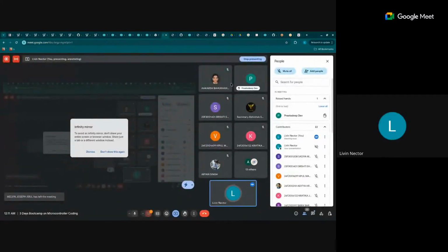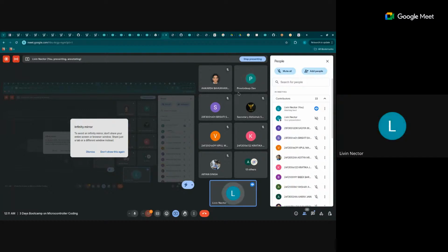A quick question, I'm sorry if it was discussed earlier. What language are we using here? It looks a lot like C. It's actually C++. Usual C++ code will have some include statements and things like that. Arduino is a framework. In this Arduino framework, we have the setup and loop functions. The Arduino IDE will have some preprocessor directives and compilation. In the compilation process, it translates and preprocesses the code into a main.c and then compiles it. It's actually C++ code.